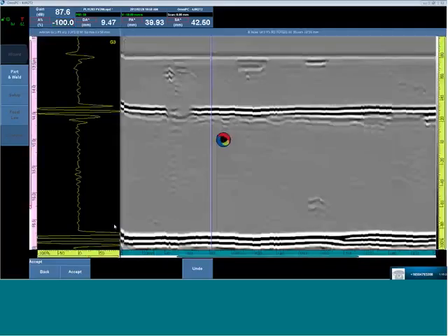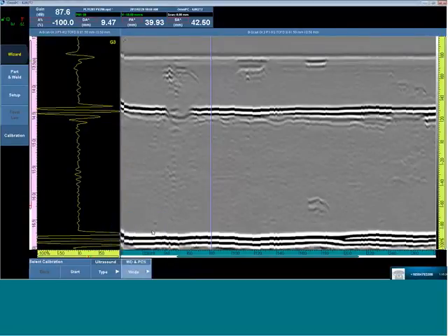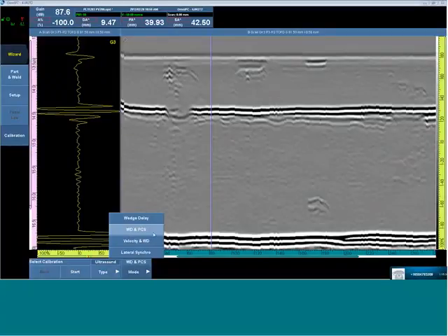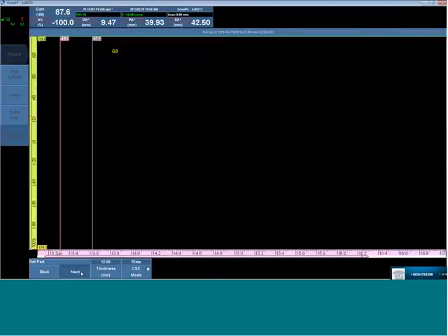Select Accept. Now we will calibrate wedge delay and PCS. Again, this is a new feature for the new 4.0 version of the software to include the PCS calibration. Take a representative A scan, enter the thickness that has defaulted from the component.